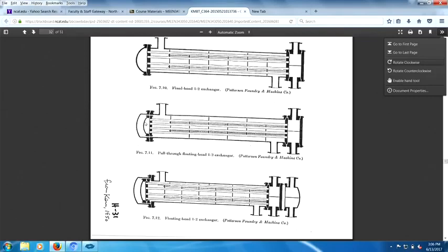And that means the thermal expansion of the tubes is such that it can expand freely. They got a lot of expansion in here. In fact, this is probably a bad design. There's so much stuff here. So the stuff comes in, the tube bundle is floating. This is called tube bundle, right? We already said that. And so that takes care of the expansion on this.